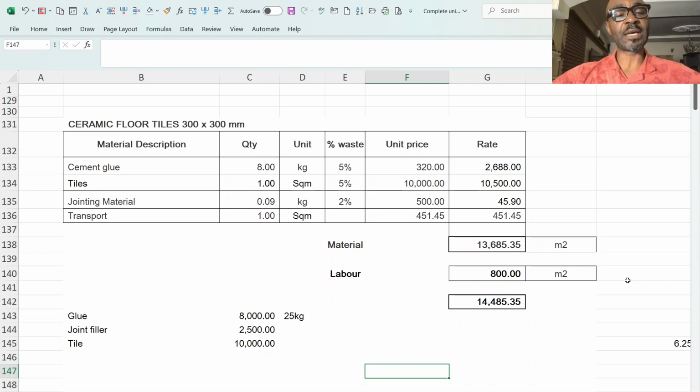As we all know, there are two approaches to laying tiles. One is referred to as wet lay, where you do the screeding, then instantly mix the cement slurry, spread it on top of the wet screeding, and begin to lay.